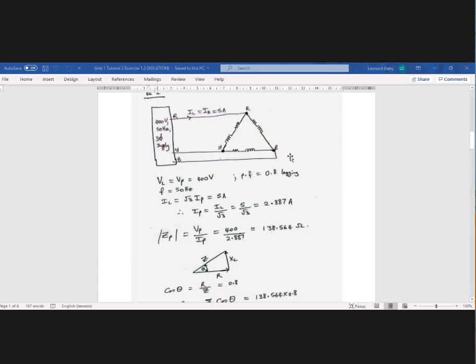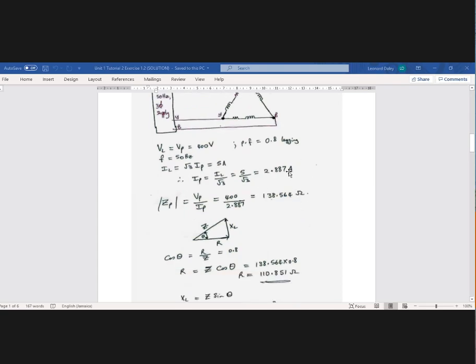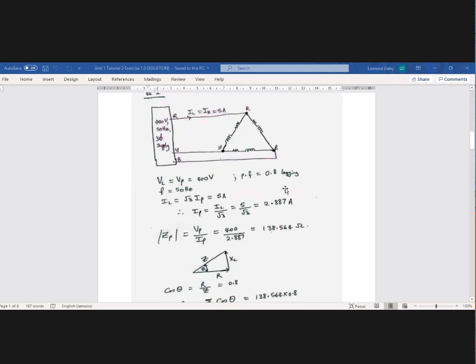All right. So what you have to do now is remember, what I don't know. You find the line current, the phase current. Yes, sir. I got the 2.87, and then I found the angle. So the angle you found would be the angle based on what? Based on the power factor. Right, the power factor. So it would be the cos inverse of 0.8.